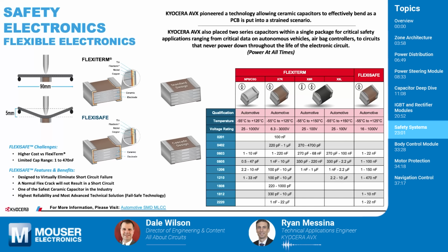So here we have one of the staples of an AEC-Q200 part, or an automotive qualified part, and that is FlexiTerm. FlexiTerm is basically just making sure that you have a capacitor that can withstand the shock and vibe environment that we're going to get out of either a vehicle on the road or the heavy vibrations from your big farm vehicles going through a field or whatever that might be. And all it really is, essentially, is what it says. It's a flexible termination. It's a silver flexible epoxy that goes between the nickel and tin portion of your terminations, and it just allows it to absorb some bend and some shock.